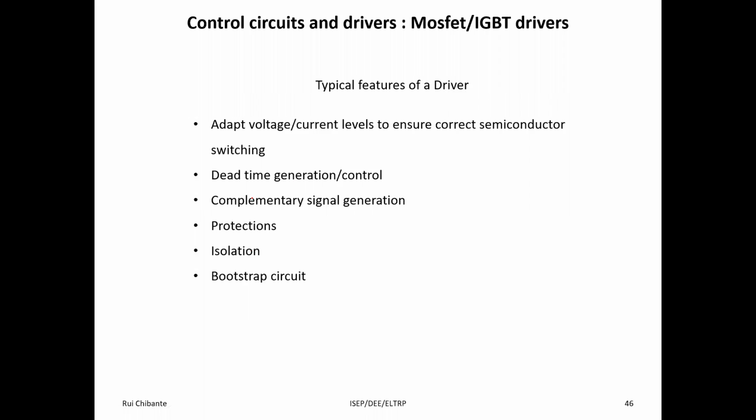I already mentioned in the last class that sometimes we need to have a dead time or a complementary signal, so drivers can provide these functionalities, as well as other functionalities such as protection in terms of overcurrent, and isolation between the control part and the power part. Okay, we can electrically isolate both circuits using this driver.